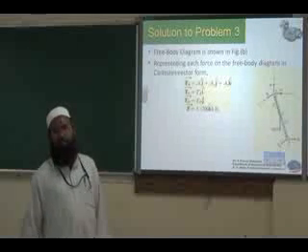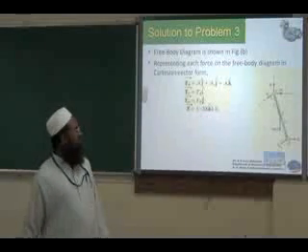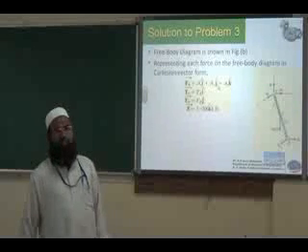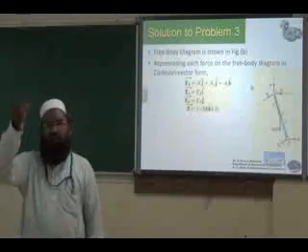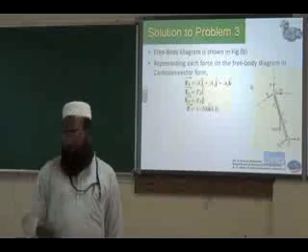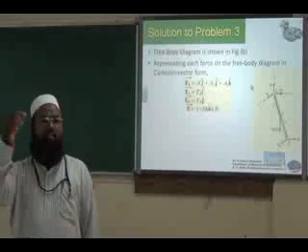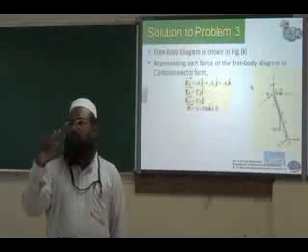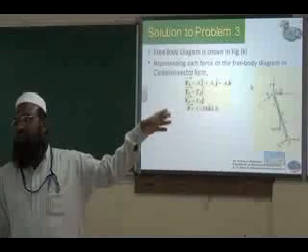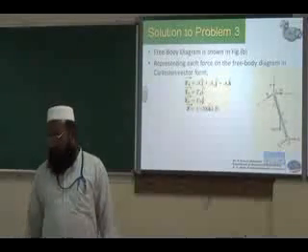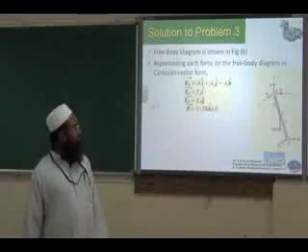A force acting at point A. There are 3 forces. You can sum them up as a resultant force acting at point A as AxI plus AyJ plus AzK. It is similar to the problem which we did in 2D. If you remember that bell crank lever problem, it was a hinge joint. The hinge joint cannot move in X or Y direction, so the 2 support reactions we replace with a single resultant. In a similar manner, the 3 forces Ax, Ay, Az, we represent as a single force in Cartesian form, written like this.